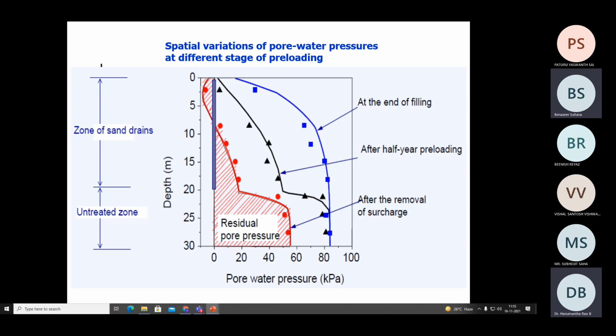Below 7.5 meter, positive pore water pressure means there is some amount of water, and that water is also bearing a small amount of the load. No water and water. From 0 to 5 meter there is no pore water.